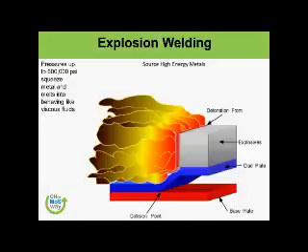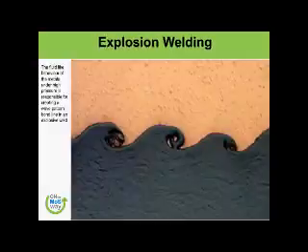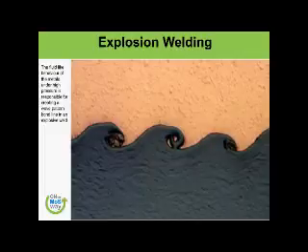So what we do is use explosives to bombard it, and of course the collision point is happening, and this is how we keep bonding these two plates, the base plate and the top plate. Okay, so with the heat and the explosion process, the metal is bonded literally like this. It could be aluminum bonding with steel, or two different metals being bonded.